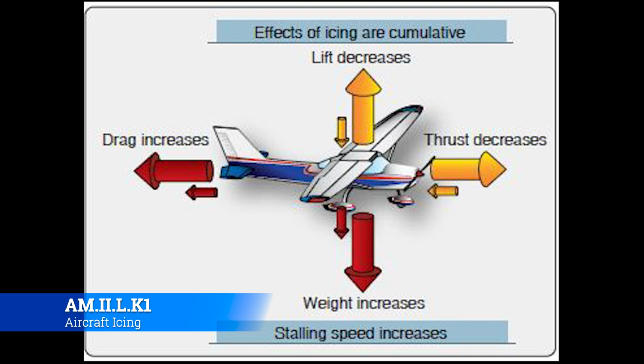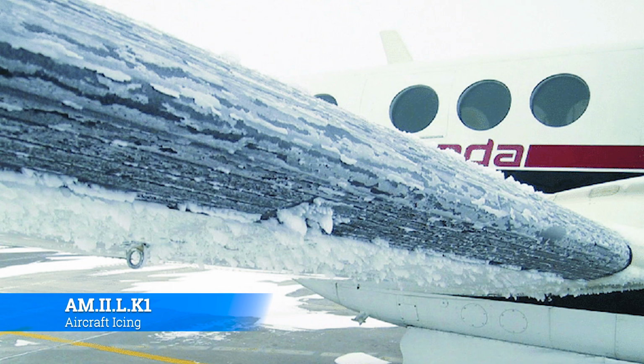If ice forms like it did on that airliner, on the flight controls, they could get jammed up, and then you'd end up having to yank on the controls to see if you can potentially break that ice off. If it's gotten to that point, you're probably not going to be able to clear the ice, and you'll end up inducing some sort of adverse control that you don't want, and then into the ground you go. Okay, a couple examples of ice on aircraft.